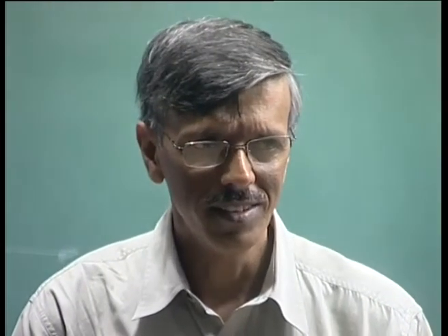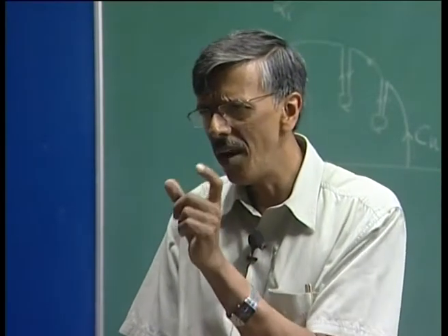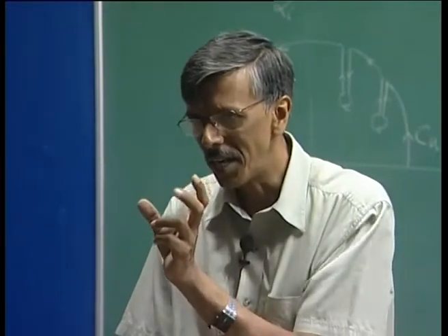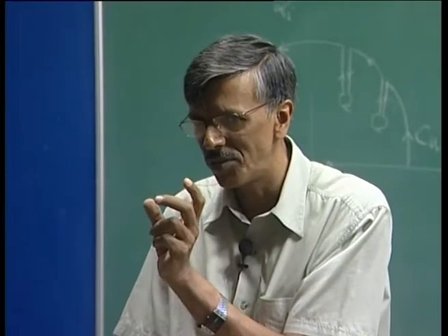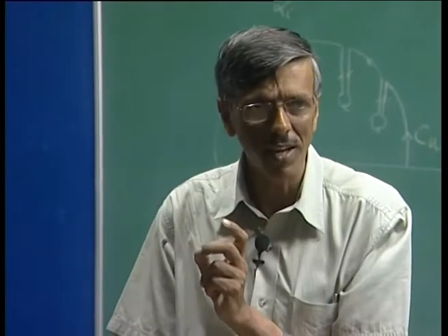I have a uniform flow. I am creating an excitation. What is the consequence? I am creating a stress field that strains the fluid, and the strain rate is proportional to what? The curvature of the streamlines. And if I create very large wave number, I am creating waves which actually distort very rapidly in small region, and with alpha going to infinity, the strain rates are going to go to infinite value.